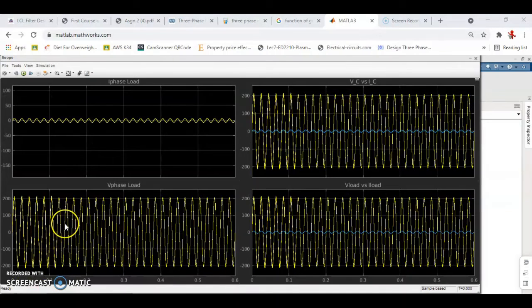Next, if we see the voltage and current across the load, we may notice that the power transferred is 2 kW to the load once the switch is connected. Then, on the display at point C, which is the output power at the load, for this condition is almost 2 kW, but the output power at point D at the grid is actually equal to 0 because there is no current flow to the grid. Even though the display shows some current to the grid, it is actually almost zero.